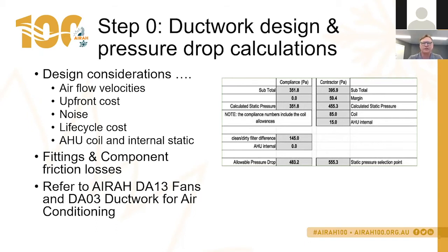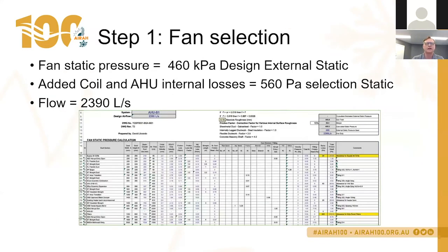The allowances in the code are clean filter allowances. So the code will come up with a lower static pressure loss for the calculation of the efficiency value than what you will get when using your own calculation. So that table there gave you a comparison.